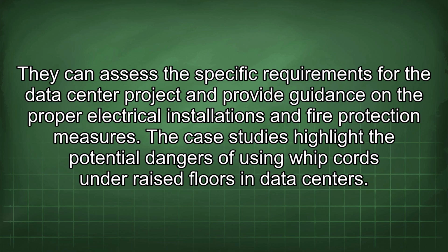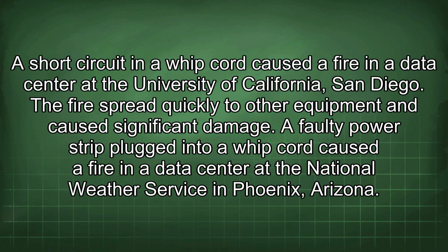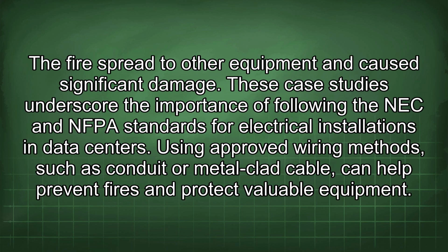The case studies highlight the potential dangers of using whip cords under raised floors in data centers. A short circuit in a whip cord caused a fire in a data center at the University of California, San Diego. The fire spread quickly to other equipment and caused significant damage. A faulty power strip plugged into a whip cord caused a fire in a data center at the National Weather Service in Phoenix, Arizona. The fire spread to other equipment and caused significant damage.